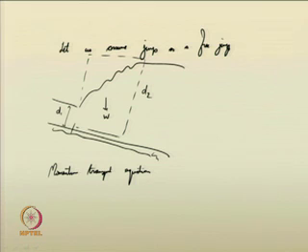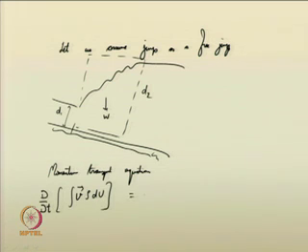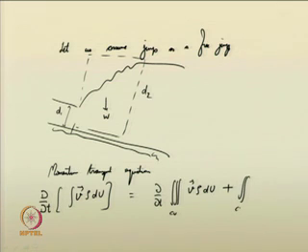If you recall the momentum transport, then using the Reynolds transport theorem, I am just again writing it for your benefit. This is the volumetric integral. This is nothing but the time derivative of the volumetric integral of v rho dV plus the areal integral of v rho v dot n dA.